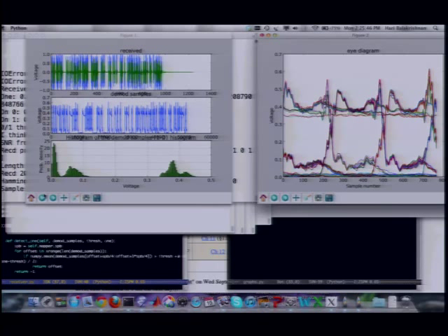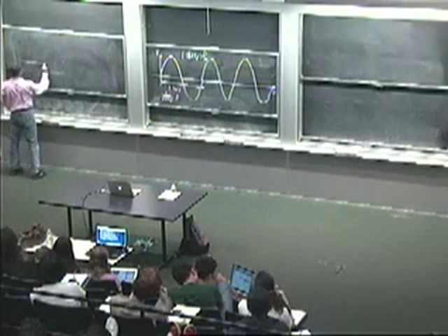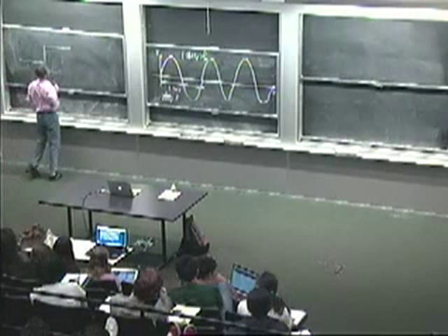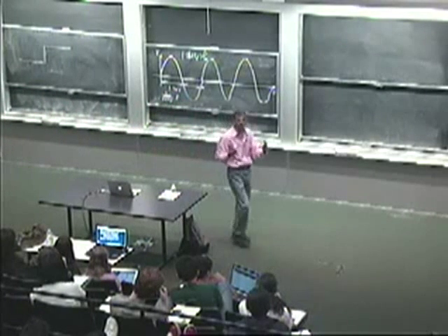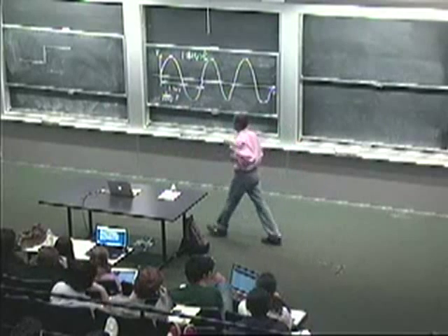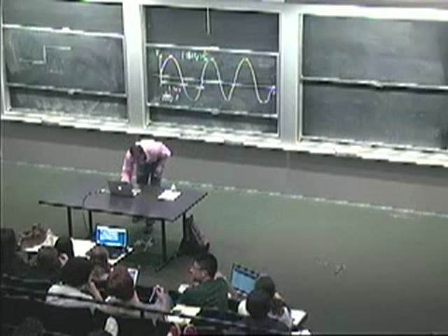Now, on this channel, there are 2 things that distort the quality of communication. The first is noise, and you kind of saw the effect of that. The second is this thing that we've been studying by modeling it as a linear time invariant system. The idea is that when you have a sequence of zeros on the input and then you go into a sequence of 1 samples, that sudden sharp input transition does not immediately get captured at the receiver. It takes time for the 0 to settle into a 1 and a 1 to settle into a 0. And you can see that in this picture here.